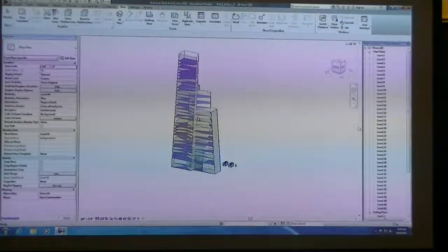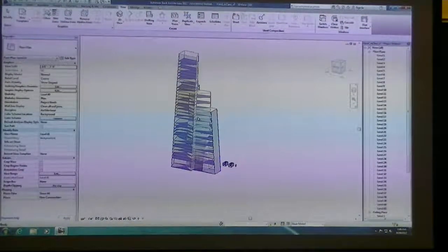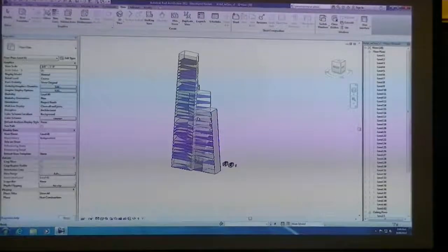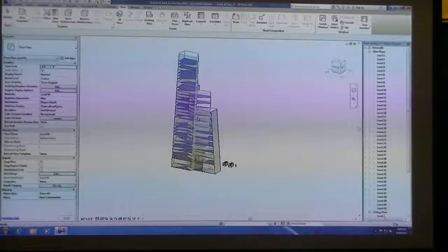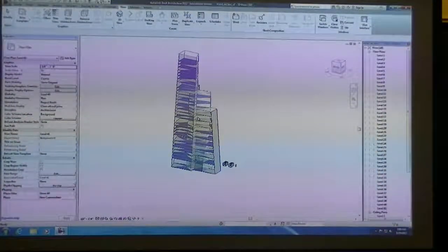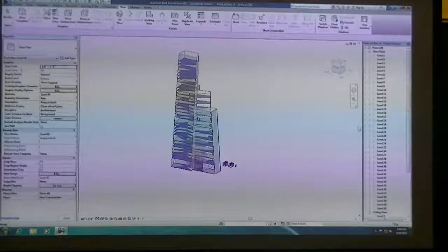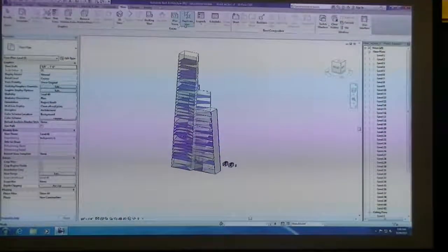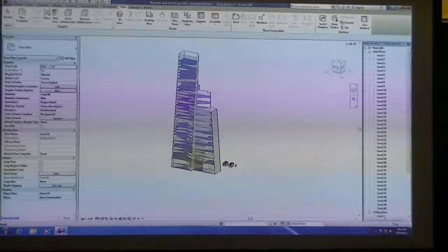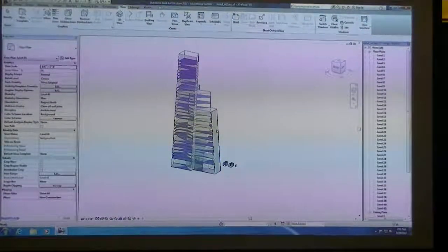So you might have deleted the datum lines. Yeah, I did. So if you delete the datum lines, that's why your views went away. Right. So you never want to do that. But if you keep your datum lines or add them back. I just wondered how to get them back. Yeah, if you want to get them back, if you add more datum lines, you're going to have to redraw them, and then your views will come back.